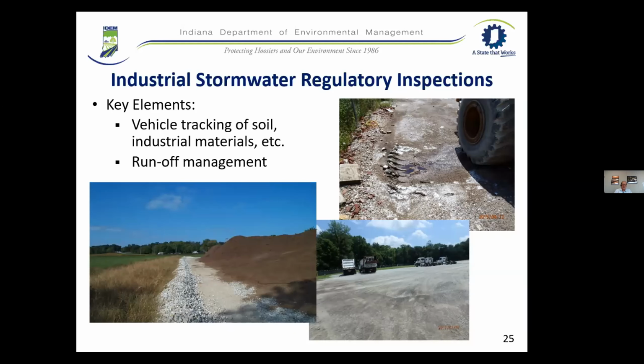You need to really look at runoff management that's associated with your facility, and maybe put in diversions or something like that that would divert the water to a basin. So runoff management is a very important tool. We typically think of runoff management probably more for construction stormwater, but it is a tool for an industrial site to manage stormwater runoff.